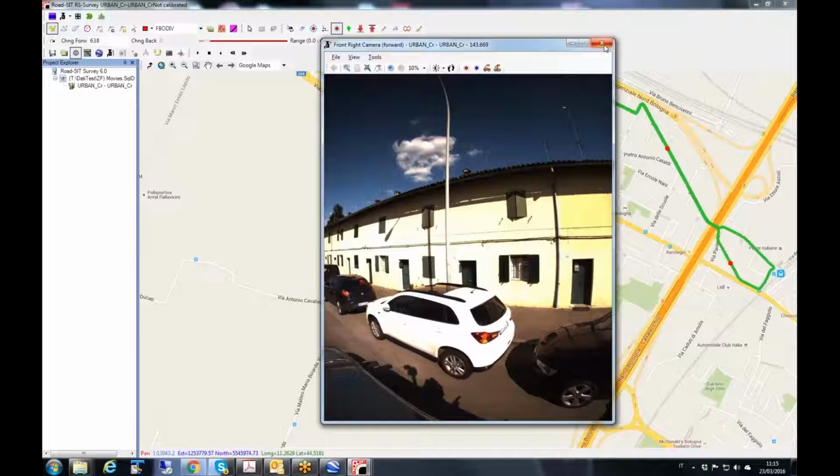For our system, for example, the GNSS antenna is linked to the Ladybug. If you move the Ladybug from our system, you leave the IMU without GNSS signal. But anyway, you can mix up a stereoscopic survey with our laser survey using a good amount of ground control points. It's not a problem.